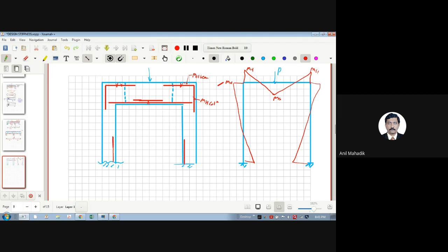So here on this side and here on this side, main steel. And generally we extend beyond the point of contraflexure. Okay, and then I will provide minimum steel. अभी ये जो steel रहेगा column का मेरा ये वाला. So generally we cannot curtail in the columns like this.